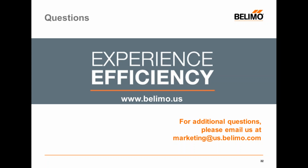Okay, Steve, are you ready for that first question? Sure am. Okay, what is the most common smoke control strategy? Well, as I referenced in one of the earlier slides in the presentation, the most common smoke control strategy is what's called containment, and that is simply a fire smoke damper or combination fire smoke damper assembly connected to a duct detector or a fire alarm system, and it's used to contain smoke and fire to a specific room or area of a building.